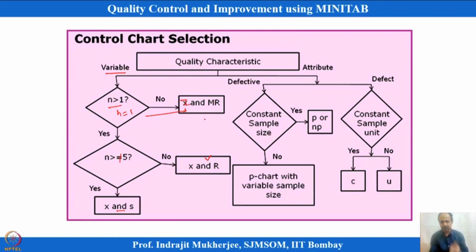All these charts can detect shifts of higher magnitude. Whenever there is a mean shift of higher magnitude, it can be seen immediately in the control chart and it leads to a special cause or assignable cause. Points will go outside the control limit lines frequently, which indicates that the process mean has shifted, so I need to take some precautionary action. The mean may be higher than what is expected.